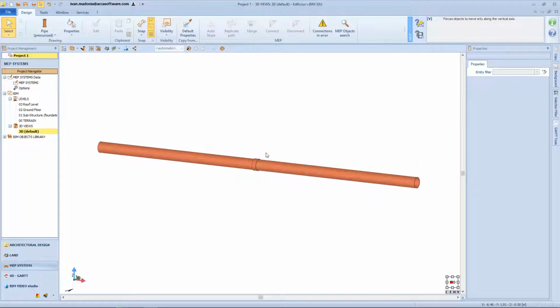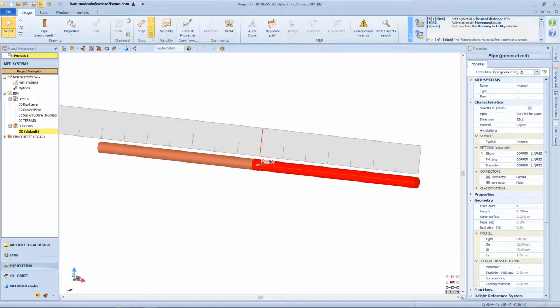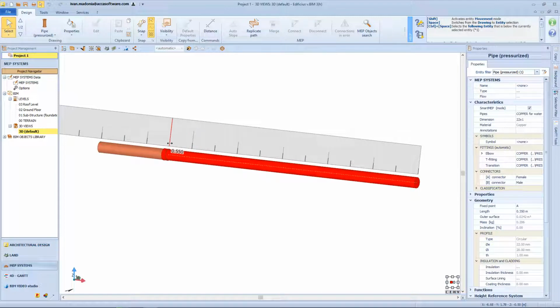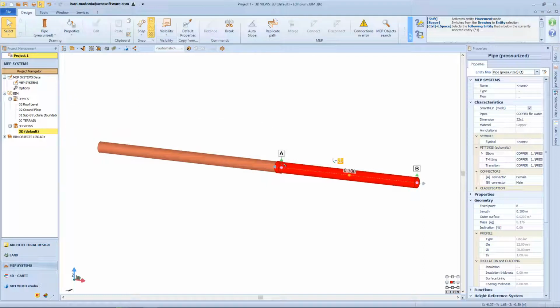The generated connection can be moved along the pipe axis. If one of the two sections of the pipe is selected, the gray arrow appears allowing you to graphically modify the length, while with a joint, it allows you to change the length of the selected section, leaving the connection unchanged, thus resulting in a rigid displacement of the connection along the pipe to which it belongs.